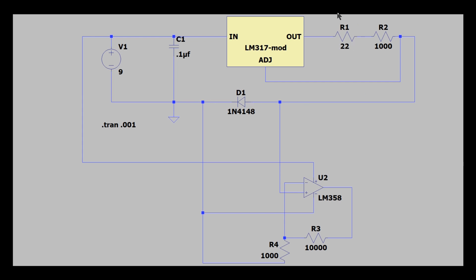Now you say, well, okay, why is this resistor in here? Well, the problem with having the pot on here is you can turn the pot all the way to 0 volts. That means that you can drive the current of this unit way up there. And we don't want to do that. First of all, it's going to get hot. Second, your diodes probably can't handle the kind of current it's going to deliver temporarily. So this is kind of a limiting resistor. This makes sure we don't get out of control too far. And that way when you're at 0, you're still limited on current somewhat.